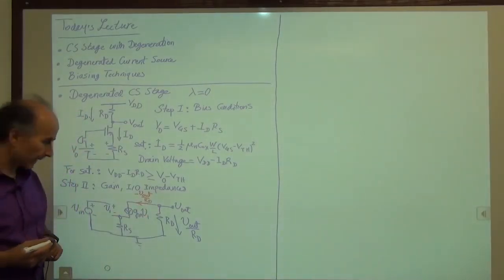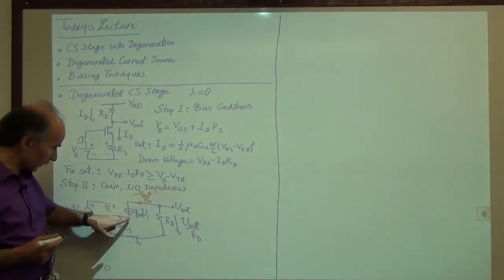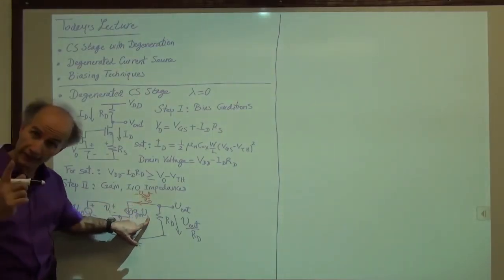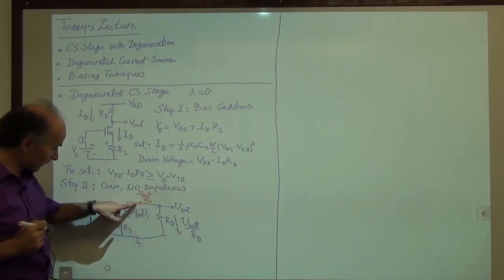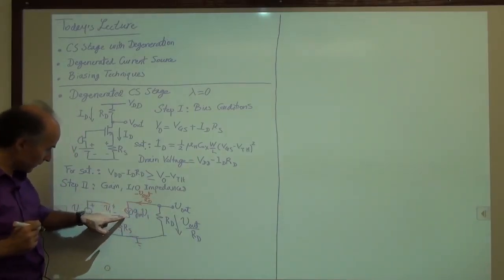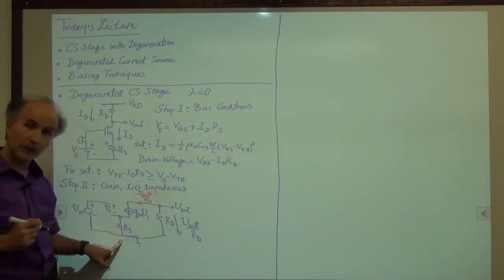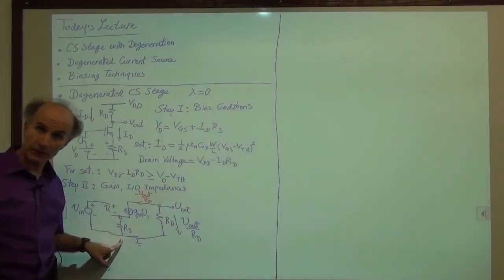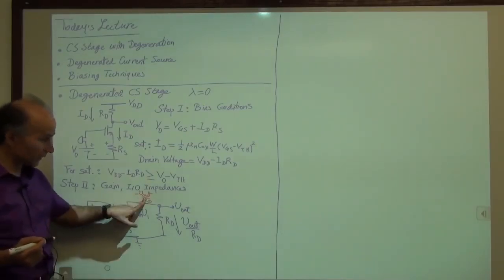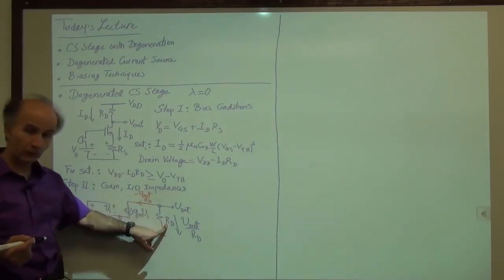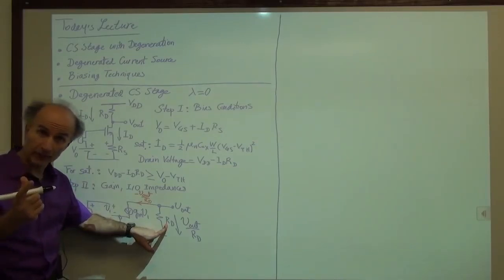Okay. All right, now this current happens to be equal to gm V1. So that's interesting. But there's also one other interesting point. This current flows through here, and flows through RS. It has nowhere else to go. So the current through RS happens to be this current, which is the same current as through RD, except with a negative sign.